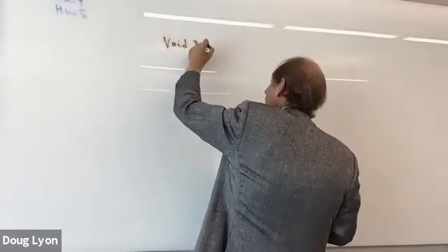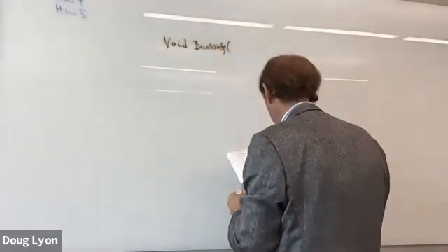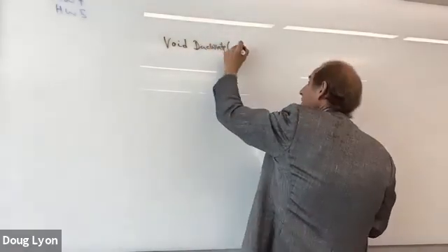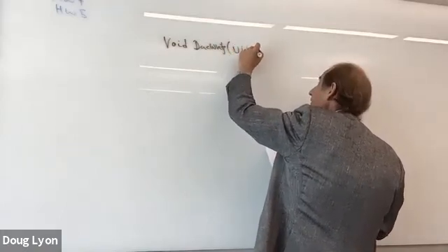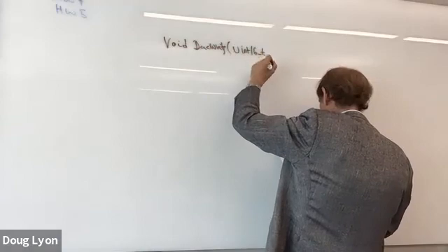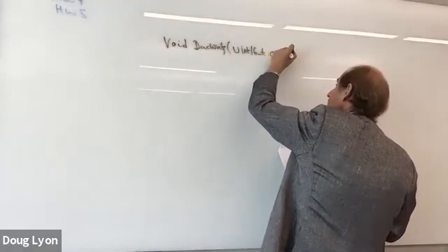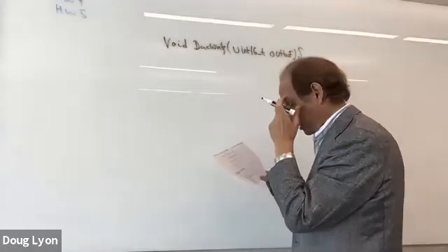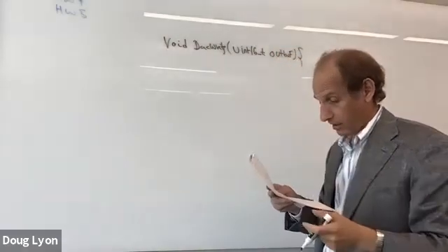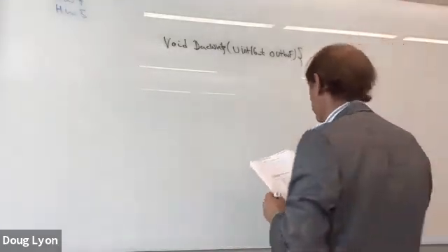So here comes the DAC write. And what you'll do is you'll take an unsigned integer, a 16-bit quantity, and that'll be some part of your output buffer. And now what you've got to do is change some bits at the beginning. You don't need 16 bits.